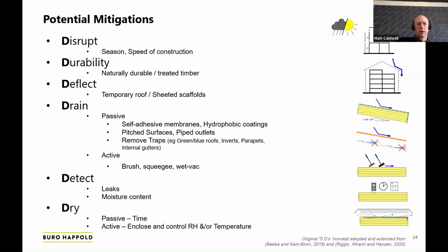Is using naturally durable timber or treated timber relevant? It really only buys you time. It doesn't get rid of the problem. Can you deflect the water away from your part-built structure? Could you have a temporary roof or sheeted scaffolds, certainly for part of the construction stage?